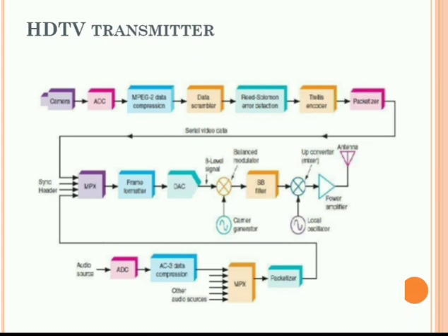This MPEG2 data compressor processes the data according to an algorithm that effectively reduces the redundancy in this video signal. Simply put, we are reducing the redundancy in that signal. For example, if the picture is half light blue sky, the pixel values will be the same for many lines. For the half line, for the full line, for a number of lines, the pixels will be similar. That is how we compress the data, by reducing the redundancy.